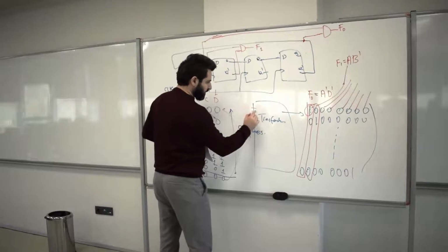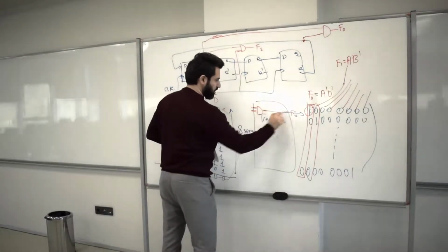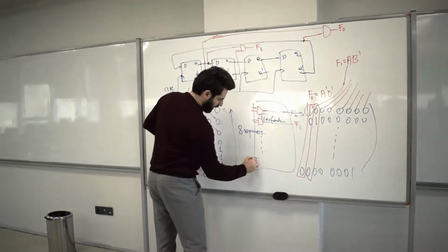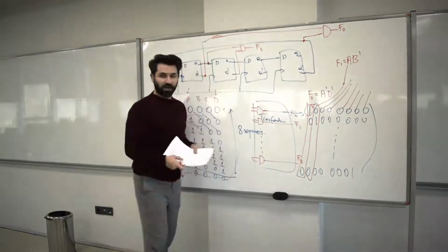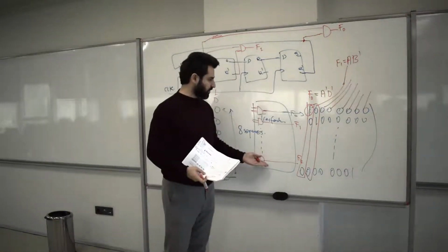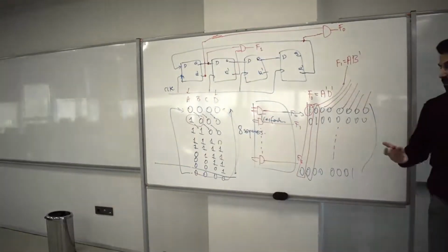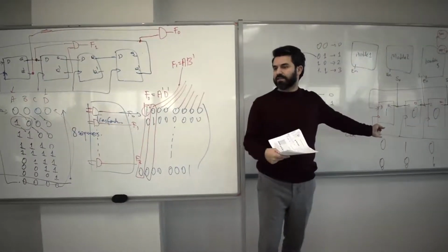So therefore, there's going to be a single AND gate to generate F0, and then a single AND gate to generate F1, and so on, and then another gate to generate F7. Okay, now we talked about this transformation. Now I can generate a counting format that is identical to the format that the ring counter generates.